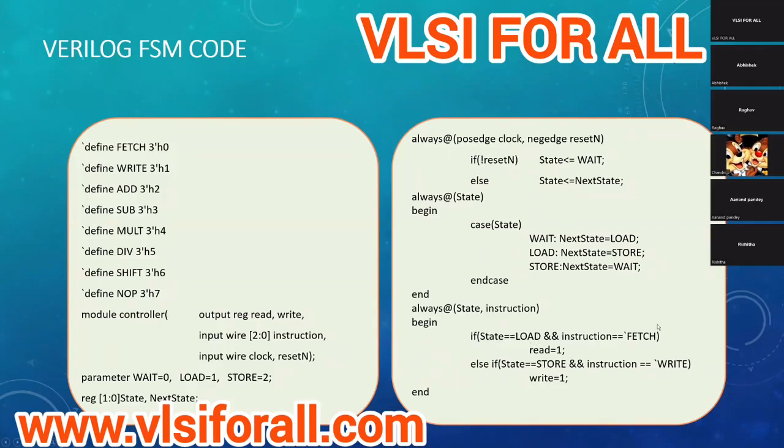So when it's in the load state and when the instruction is fetch, we have to give read is 1. So the intent is very clear from the design. But if we hadn't used fetch and this load, what we would have done is state equal to 1 and instruction equal to 0, then read equal to 1. Someone who has coded it will know it, but for someone who has not coded it, it will be a nightmare to understand if there are so many files and he has to figure out what state 0 means and what instruction 0 means. So basically these enums, typedefs, defines and parameters help in the readability and the reusability of the code.